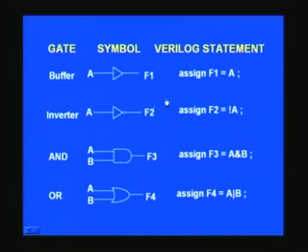And similarly, if you want an inverter, what you have to do is instead of A, just invert. This exclamation mark is an inversion signal, and this is basically a logical inversion as such. You can use it for multi-bit precision also, this very same symbol. And in this place you can use this symbol tilde, which is bitwise negation.